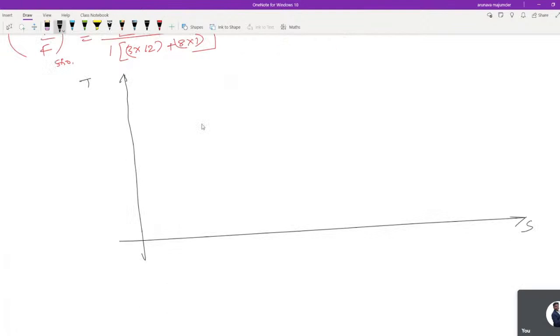We have first a diffuser. What happens in the diffuser? The air enters into the diffuser. Here we are talking about a jet engine, so the shape is almost like a divergent shape. Why do we have a divergent shape? Because we need to decelerate the speed and gradually ramp up the pressure. So in the diffuser the pressure is going to build up.